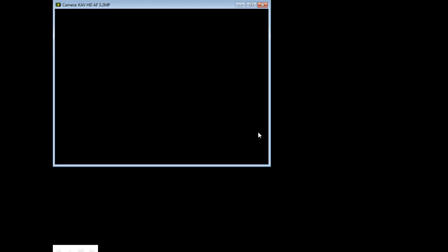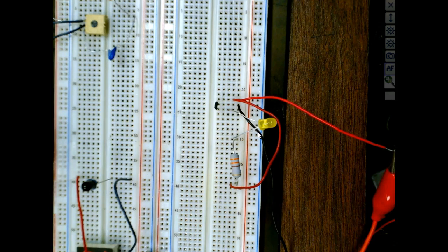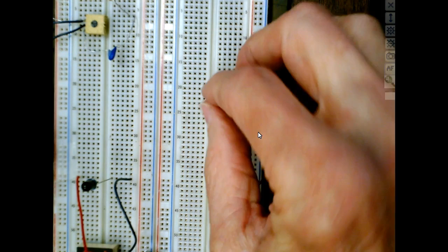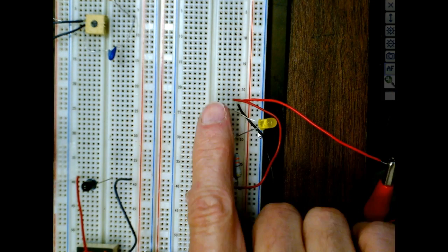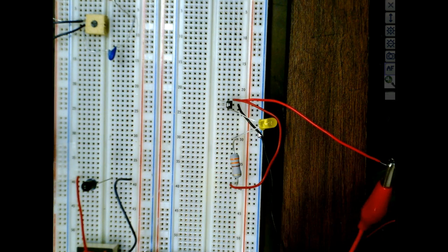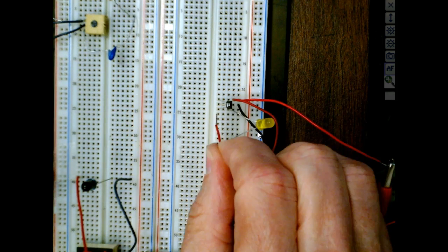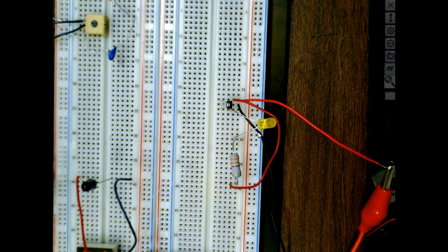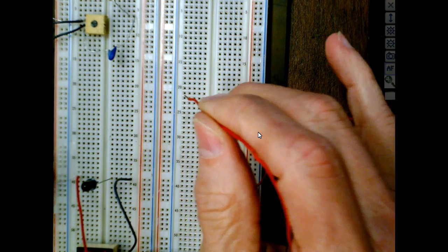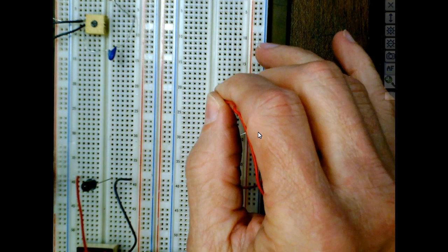It's actually in the next chapter, but it's in this section right here. So this is the Hall effect sensor right here, this little thing right here. And then if I look at it, it's got 3 leads, 1, 2, 3. Then we could look up the data sheet, and it would tell us which one is power. So on this one, this guy right here is power.